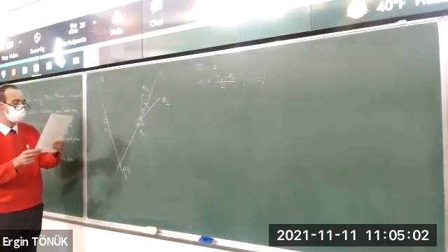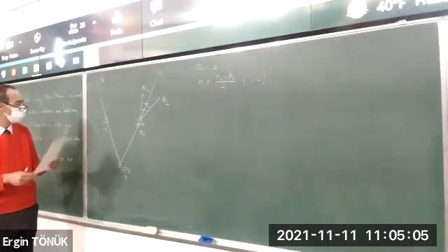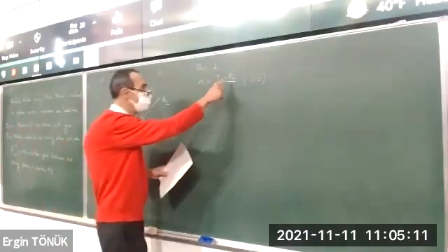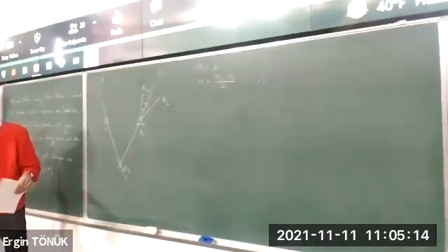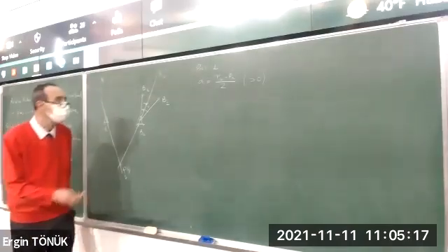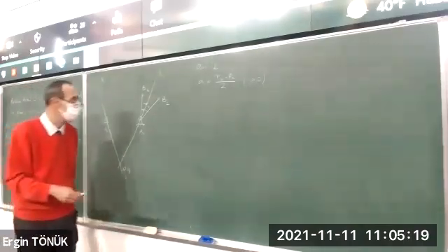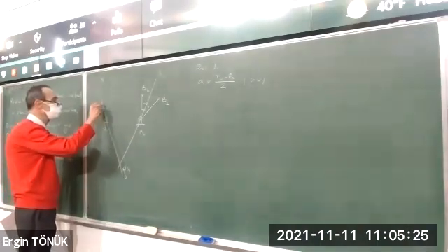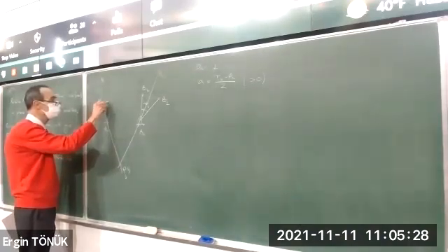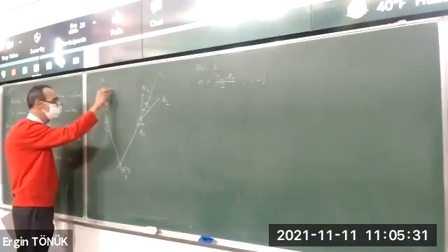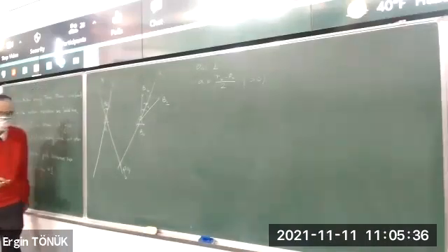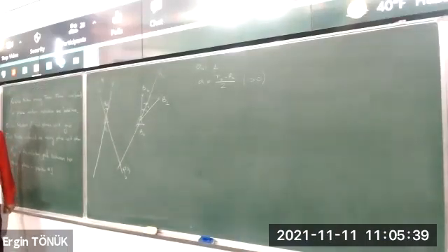Now, what I will do is, I will draw a line, capital Y, which makes half of this angle in the opposite sense. So I will also assume both of these angles are counterclockwise as well, okay, in my sketches. So I will just rotate negative phi1, 2 over 2 and draw a line Y, and I can select A anywhere on this line.